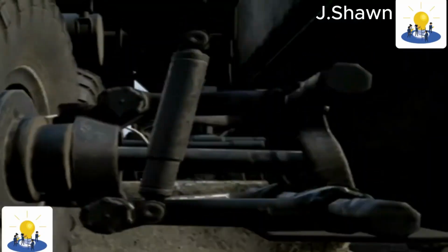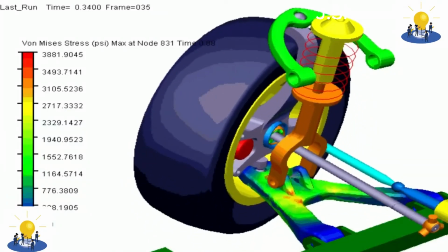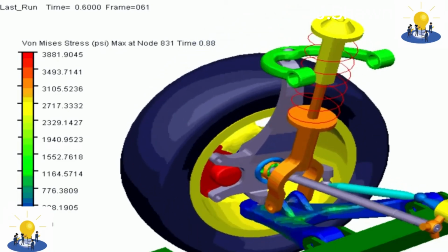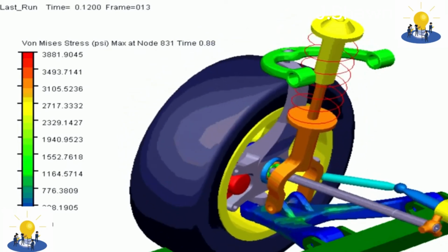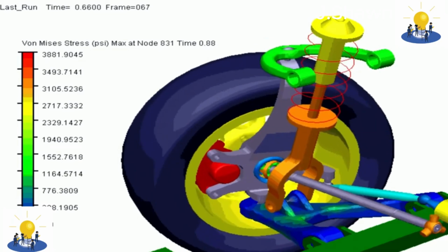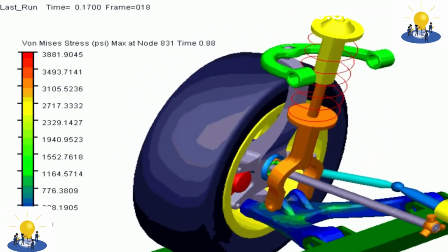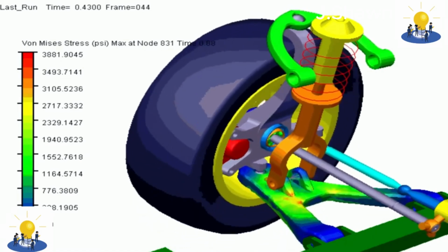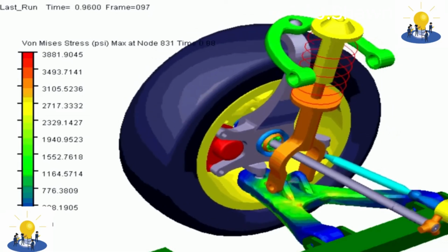When the vehicle is in a turn, body roll results in positive camber gain on the lightly loaded inside wheel, while the heavily loaded outer wheel gains negative camber. Between the outboard end of the arms is a knuckle. The knuckle contains a kingpin for horizontal radial movement in older designs and rubber or trunnion bushings for vertical hinged movement. In newer designs, a ball joint at each end allows for all movement.